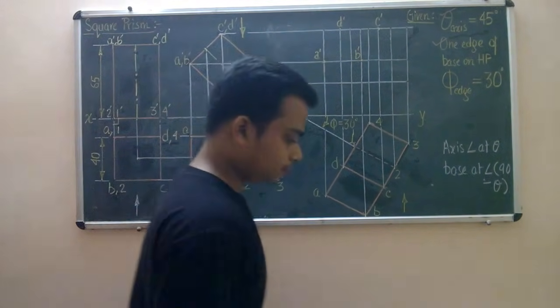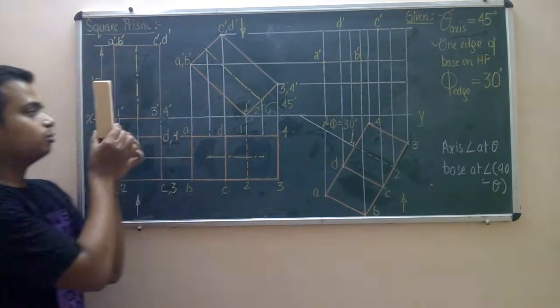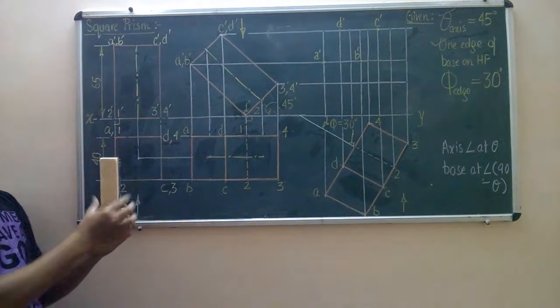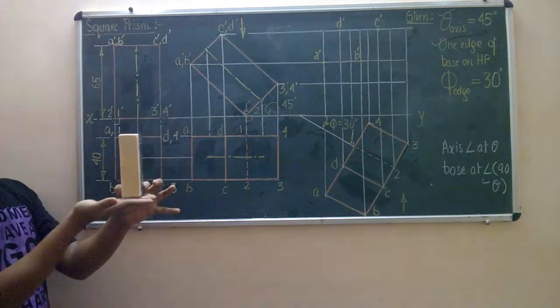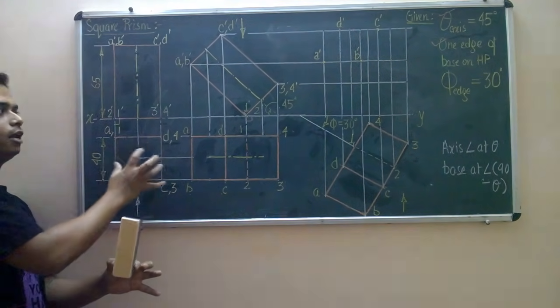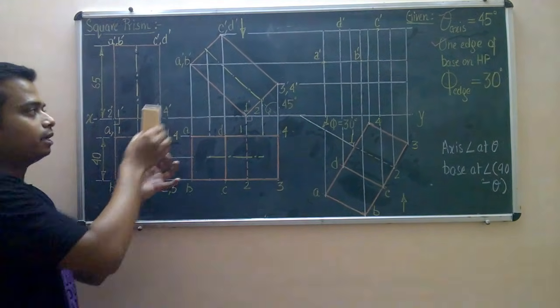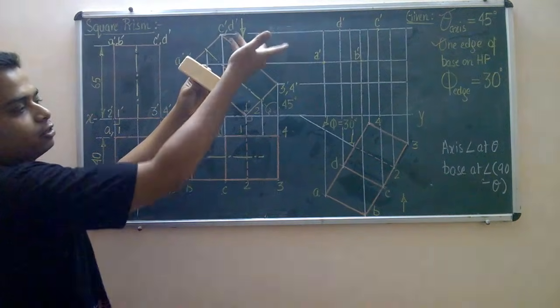Right. Now, let us take a look at this again. This was the initial position. So, top view of the base, the true shape. The true shape of this base was evident from the top. So, hence the top view was drawn and accordingly we drew the front view. Then, in step number 2, there was an axis inclination or the base inclination, you can say.